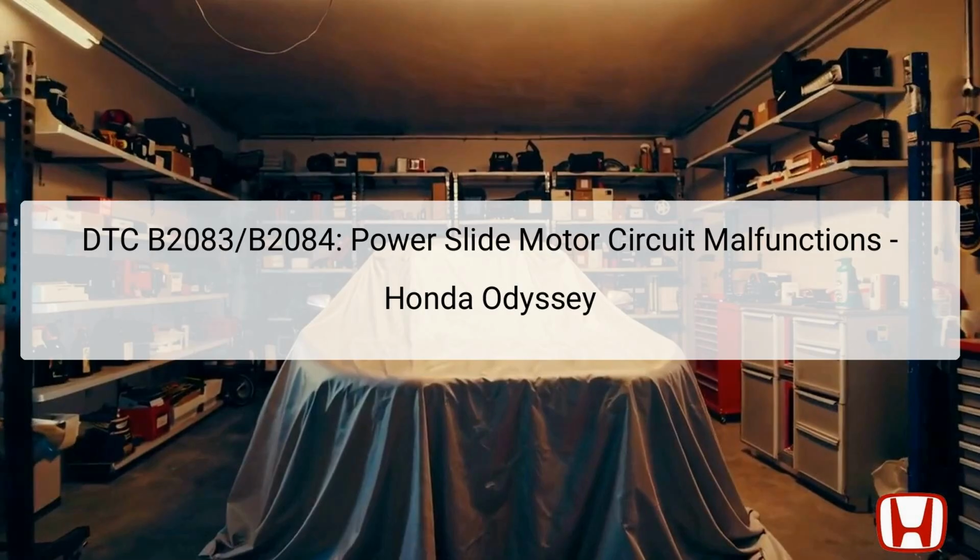The power sliding door control unit, found in the vicinity of the sliding door mechanism on the right side, orchestrates the functions of these components by managing electrical signals and ensuring power flows correctly. The electromagnetic clutch allows for manual operation of the door if required. Thus, its failure could lead to the door not responding as expected. Addressing these codes involves checking both the circuit integrity and the functionality of the components involved, ensuring the sliding door